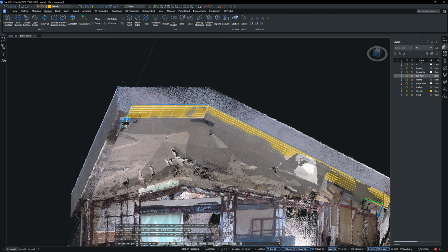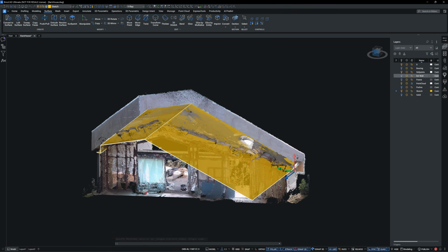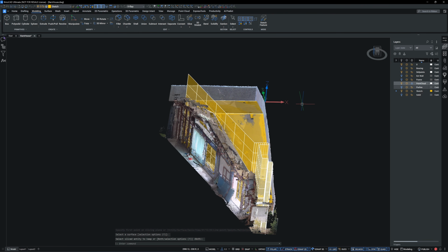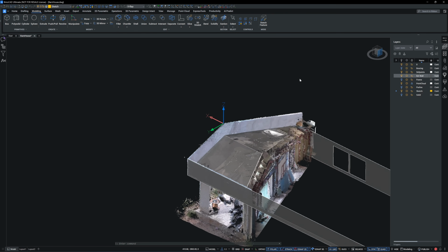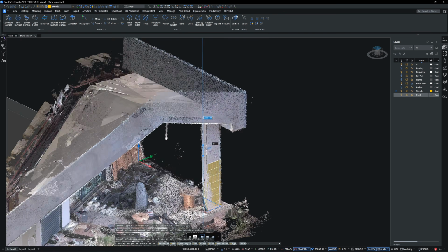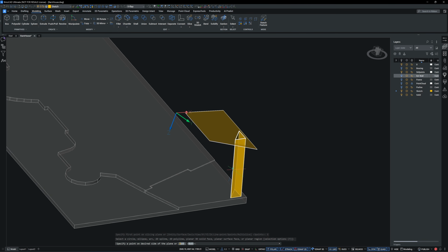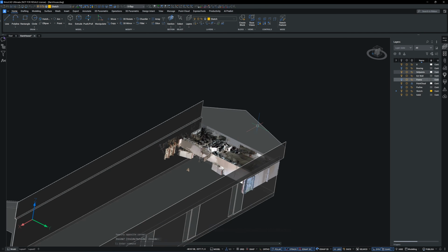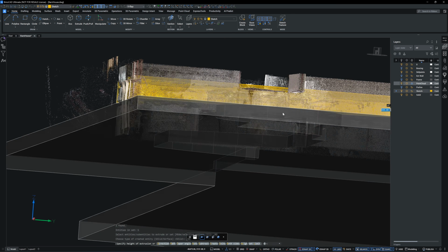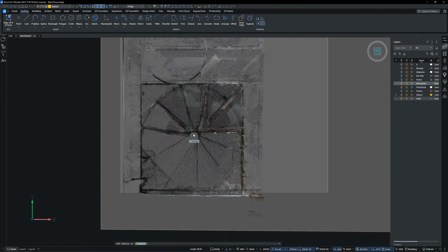Now I'm modeling the ceiling panel using the same technique. I start with lines, extrude them into a surface, thicken it into a solid, and then trim it to fit the ceiling profile. Now I'm modeling the drywall that conceals the steel columns. Now I'm modeling the mezzanine floor slab. The floor slab is supported with a steel joist, so it occupies more volume in the structural model.